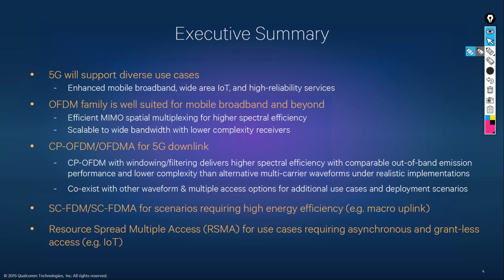So basically you need to support all at the same time. There is no single technology that can meet all these requirements simultaneously. To achieve that, we proposed configuring the subcarrier spacing and symbol duration in OFDM and making it so flexible that we change it according to the scenario.